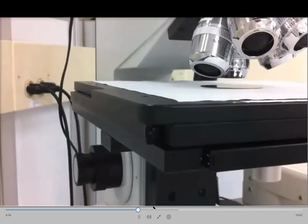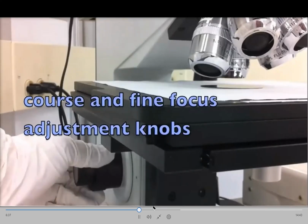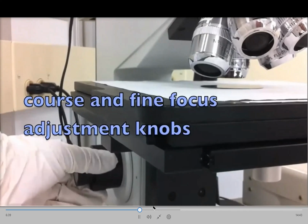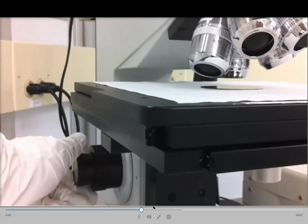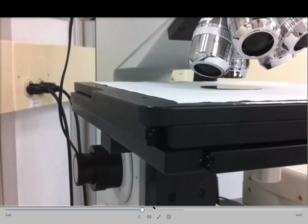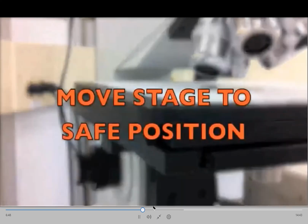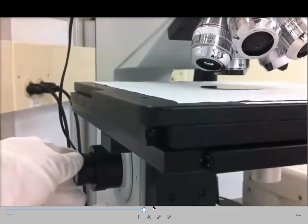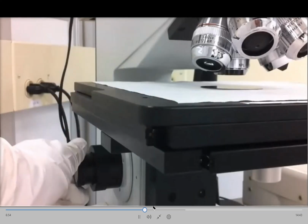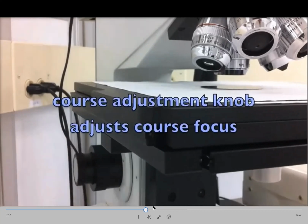On the left side of the tool, we have the coarse and fine focus adjustment knobs. These knobs are used to move the stage and sample up and down along the Z-axis. We begin with the coarse adjustment knob for two reasons. First, it's used to move the stage to a safe position, far below the objective lenses, before loading or removing a sample. After this, it's used to make coarse focus adjustments.